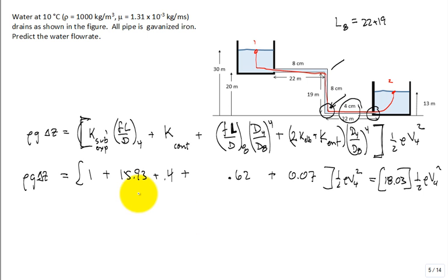So this right here is 88.4%. And then the other losses for the 4 centimeter, I lumped them together as 7.8%. You can bust them apart if you like. And these are small. It's at 3.5% and 0.4%. Really, if you have a large diameter pipe in the network, and then you reduce it to a small diameter pipe with the same flow rate through the pipes, the large diameter pipe has really small, negligible resistance, and that's what we're showing.